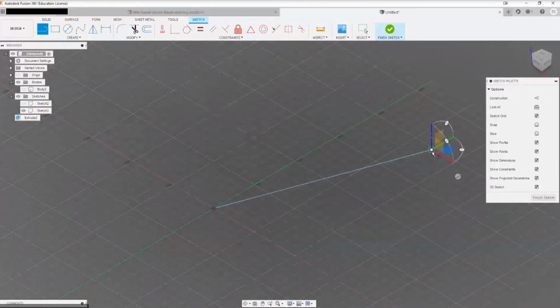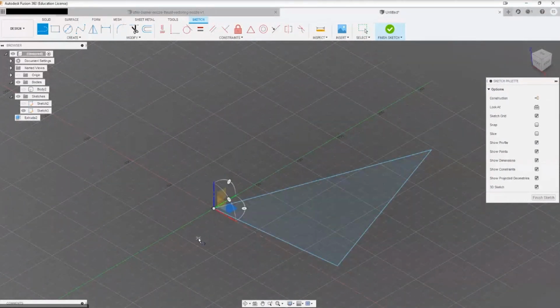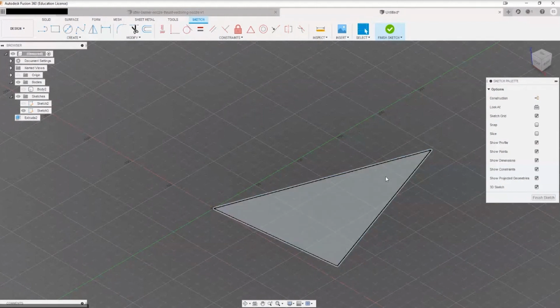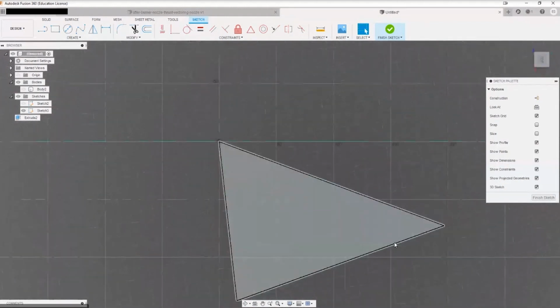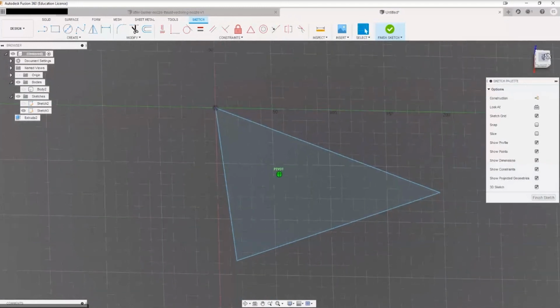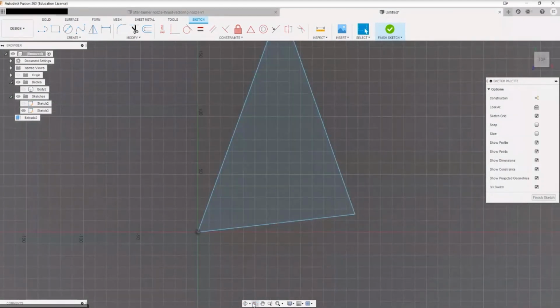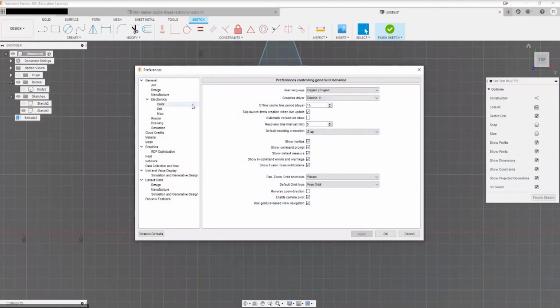So imagine if I create a couple of lines here. Yeah, what's up? When I make a sketch, it goes flat when I make the axis. How come yours keeps the X, Y, and Z axis? Oh, right. Okay. This is something in the settings that you can set for it to automatically look at whatever plane you're working in. I believe it could be under the look at function over here, or under the preferences. You can specify whether it automatically looks at your sketch surface.